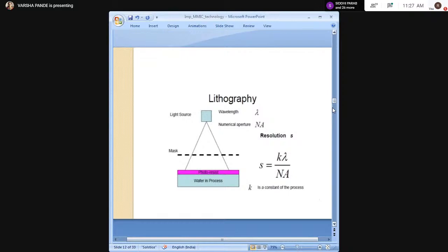Now you know all these processes. Here several times we have to use the lithographic process, because one area should be kept open and another area should be masked, so that no operation is done on it. And normally such a lithographic process is done by using projection lithography. Why projection lithography? Because here the masks are placed above, and we want more accuracy, therefore a light source is used. The masks are placed above because the design of a mask is again a tedious task. Therefore whatever masks are generated or fabricated, those masks are protected. So generally the projection type of photolithography technique is used.